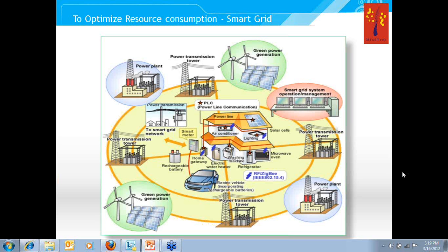That is one of the examples. So it can send instructions down to the consumers to reduce the load, say for example during the peak hours, and then also offer incentives to do so. So it can continuously transmit, for example, variable billing rates, and encourage load shifting to non-peak hours, which is called the demand response kind of schemes. They're already being implemented in countries like the US. Now it is possible only if the utilities can go all the way down to consumers.